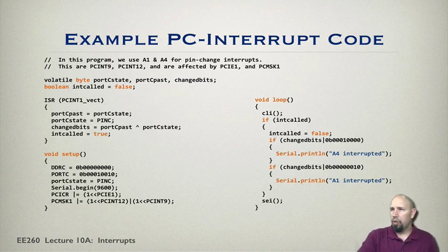What I do here is an exclusive OR, and this allows me to check if they're the same, I'll get a 0. If they're different, I'll get a 1. That's what an exclusive OR does. If they're the same, either 1 1 or 0 0, I get 0.